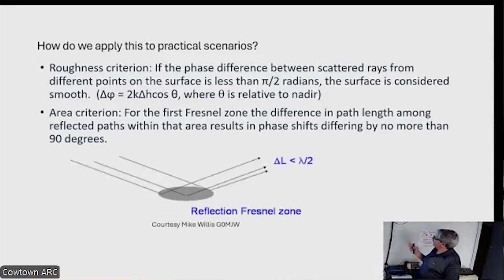There's also an area criterion, because as you make this planar surface over which reflection occurs small enough, the wave no longer becomes this specular thing, but it starts looking more like a pattern, it's diffusing or diffracting outward, like an antenna pattern in a sense. But if you want to be able to apply this idea of specular reflection, then we need to specify what the area needs to be for that wave to be treated as a specular reflector.